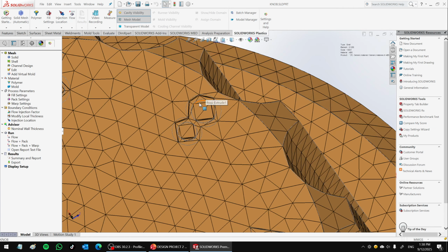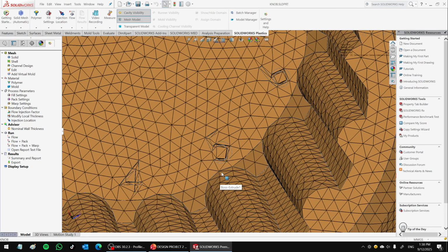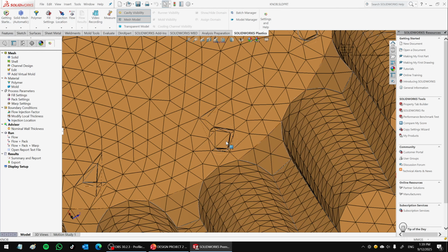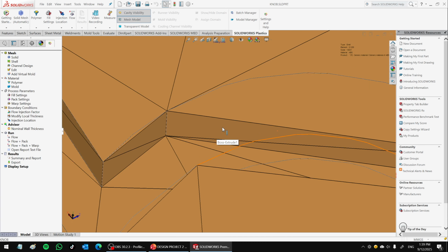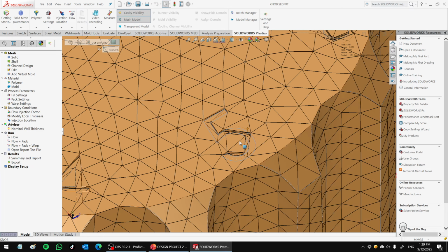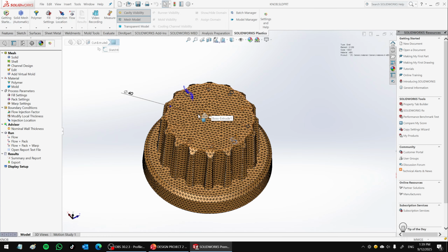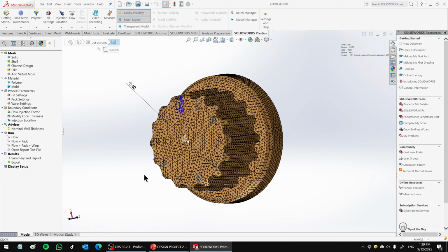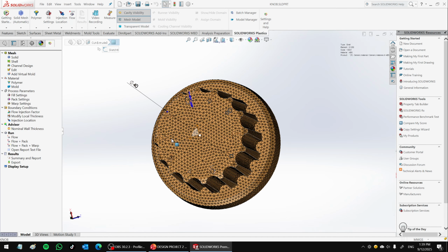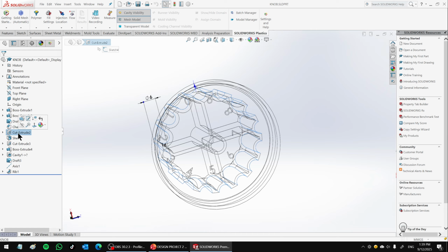You might have problems when you are meshing if this engraving number is too small. You're going to see some mesh distorted like this, right? So this kind of heavily distorted. It's okay for you to suppress the engraving numbers in order for our simulation to run easier. If we were to do that, you need to mesh again. So you can go back to your Model 3 and remove this one.